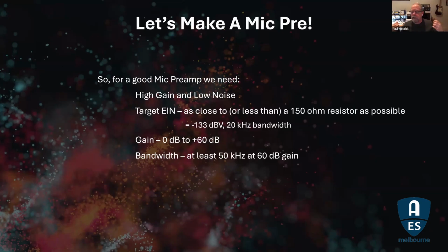It doesn't know why, but it says something is wrong. So for the best imaging, you want the phase to be as flat as possible. So I'm going to push the bandwidth out so that at 20 kilohertz, the phase is extremely flat. And that's why I have that spec.